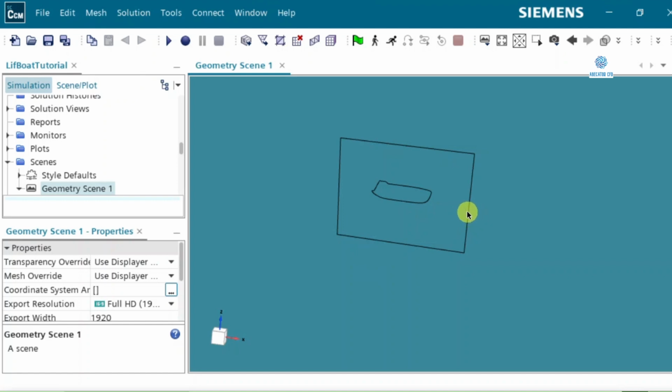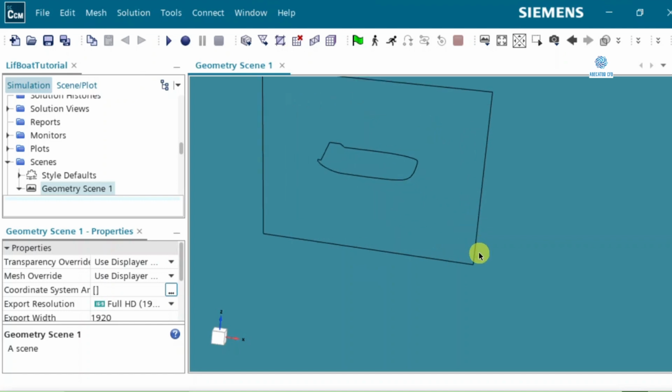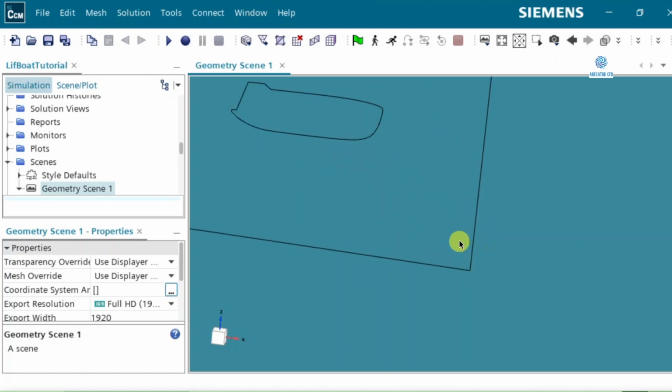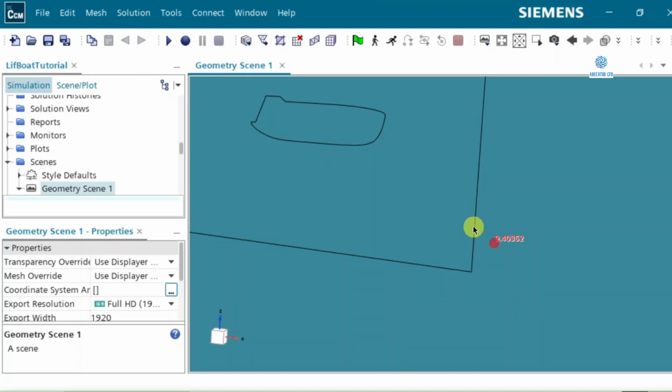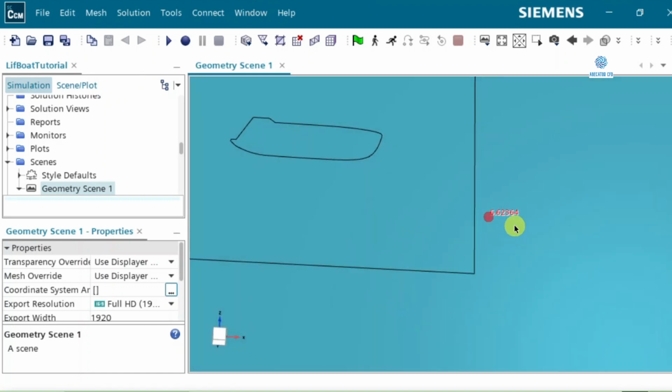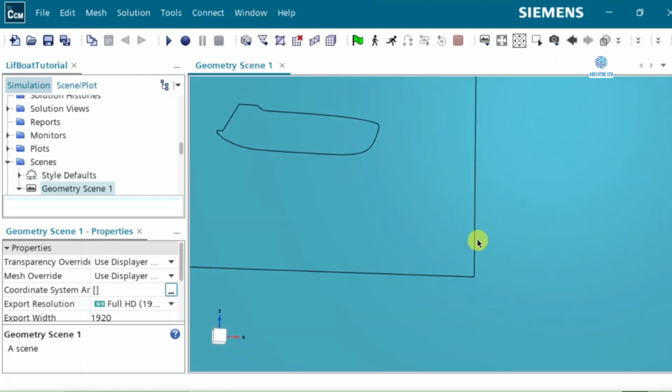Across the boundary between the overset and the background, we exchange the data. There, we solve the rest of the physics with a lower cost. There is one very important point about that interface between the two regions. The cell sizes near the interface must be close to each other. In other words, the mesh size and the cell order on both sides should be similar.